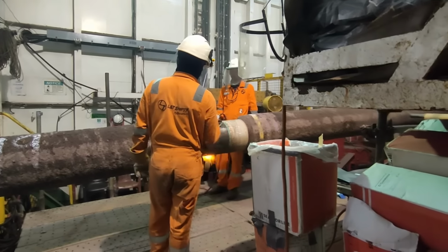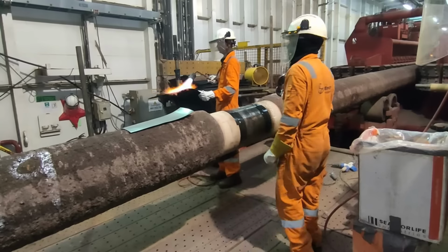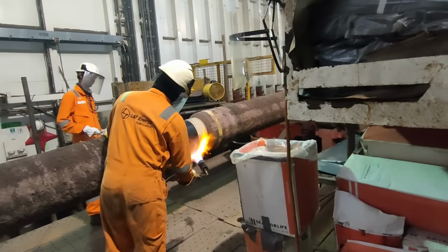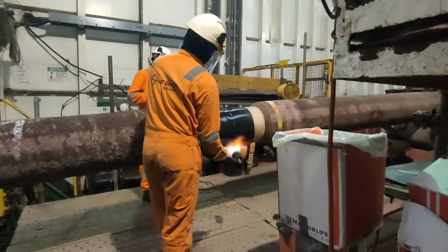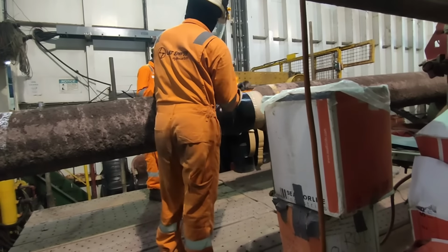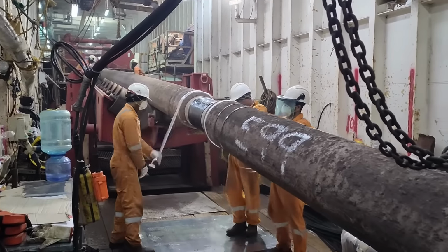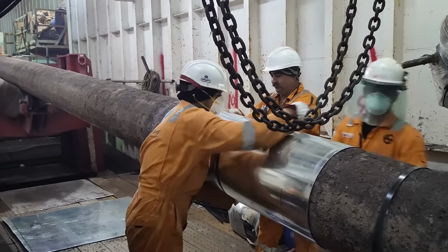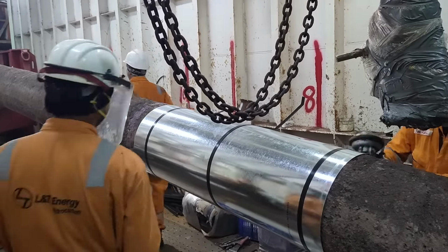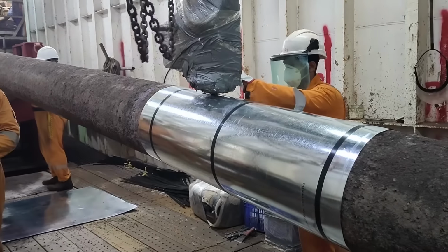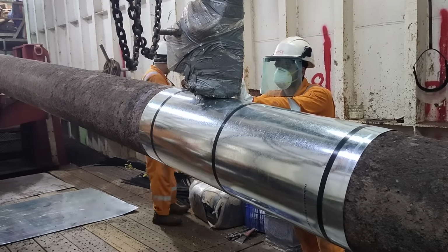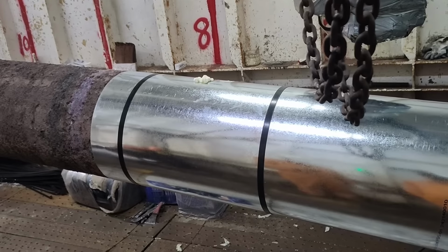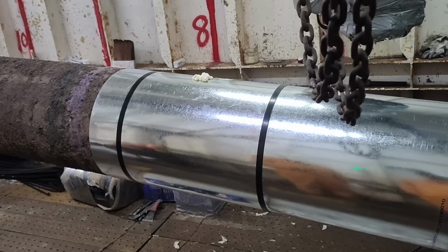Here they heat up the raw steel segment of the pipe and then wrap it around with a heat shrink material, which also prevents water from direct contact with the steel pipe. Next, the joint moves to the last station. Here they wrap the entire length of the exposed pipe with some kind of metal sheet and tie it up at both ends, and then pump a chemical mixture inside the wrapping. This mixture creates foam that completely covers the joint segment.